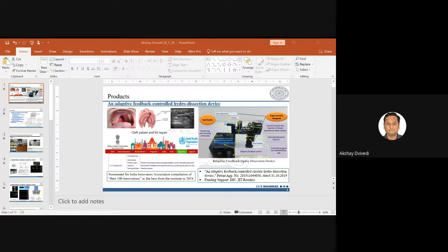So what you see here is a particular tool, wherein this tool has a particular taper, and electrolyte flows along the walls of this tool while it is moving from top to down. So basically, in the earlier case, you had this entire tool dipped into the electrolyte. Now we have removed that entire thing. In fact, we are providing drop by drop flow of electrolyte over this tool. You can see this tool and an enlarged figure for this, which shows the direction of electrolyte flow.